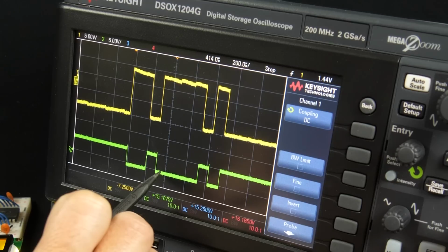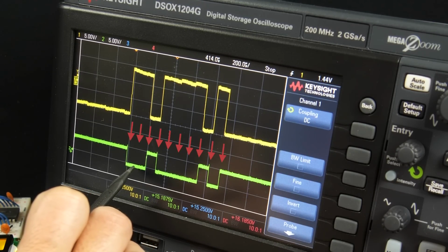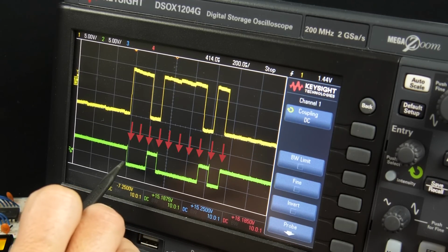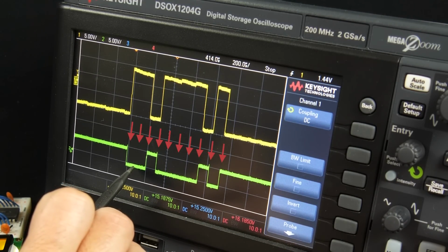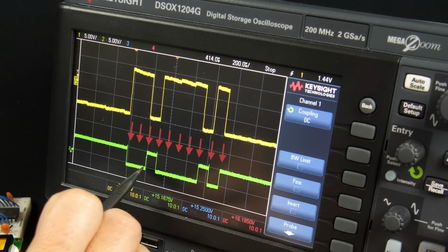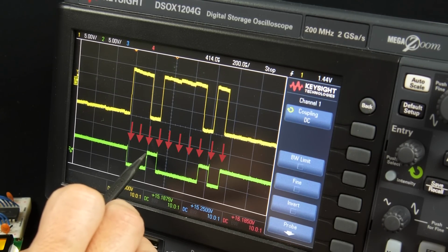We've got the timing between bits right, but if we're reading right at the beginning of the bit, we could be reading right on the boundary between bits. So if we're starting right when that start bit starts, 104 microseconds, we're reading right here. If we're just a little bit before, a little bit after, we're going to get a different value there.